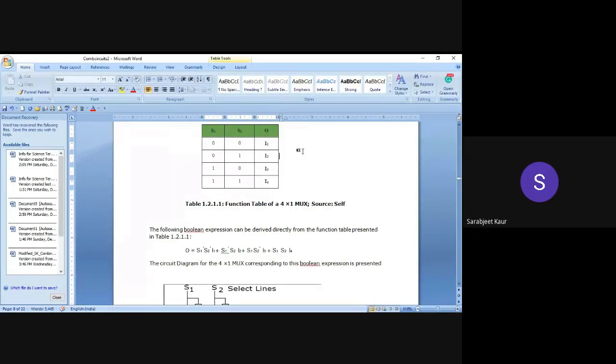Okay. So you will be learning about these concepts called frequency division multiplexing and time division multiplexing. When we talk about time division multiplexing, chunks of time are divided and given to each source.